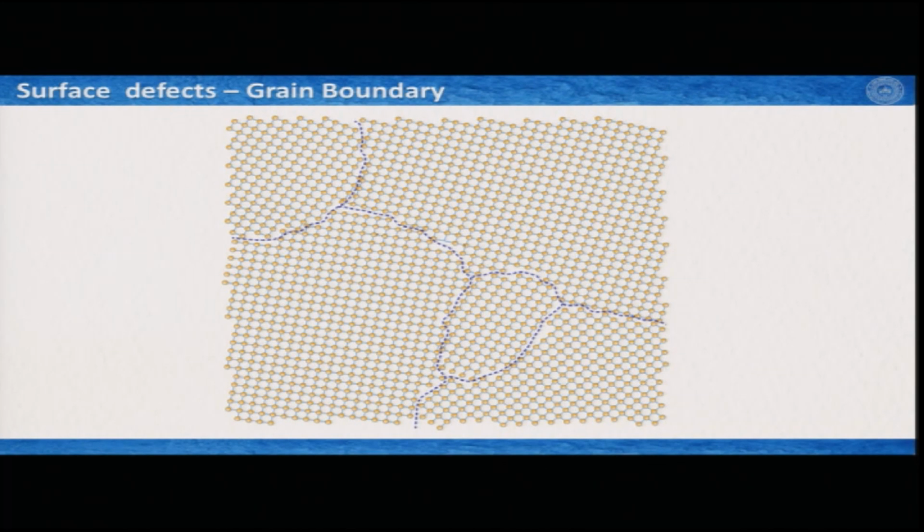So this is how we conceive a grain boundary so far. We have seen probably under the microscope different crystals, their grain boundaries and so on, but actually if you can scan it or if you can X-ray it with some inner eyes, then the individual grain boundaries are like this, these blue lines, and they are separated. Even if their compositions are very similar, they are separated because of their orientations, for example, here the orientation is like this and here the orientation is like this. So they are essentially different. For example, here the orientation is like this and here the orientation is somehow like this. So they are somehow different, and that is why we see them in a different way.